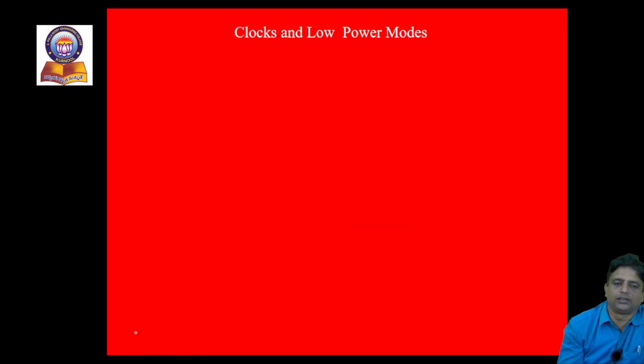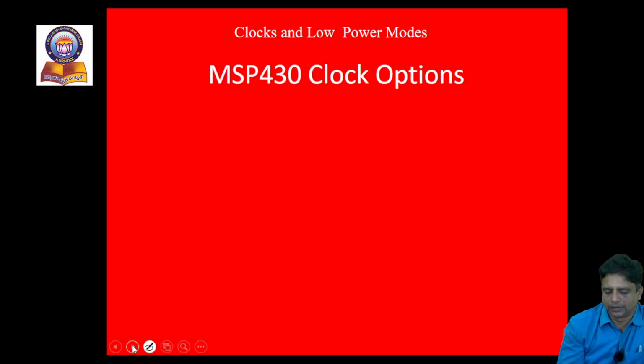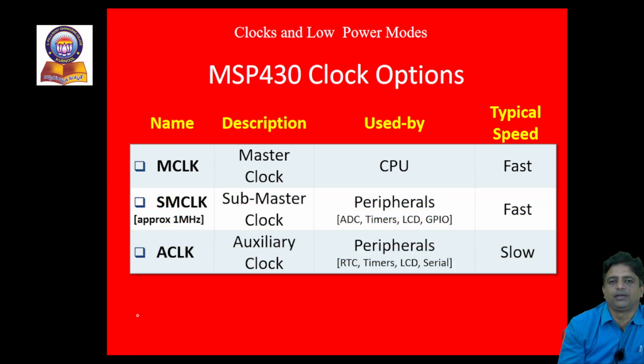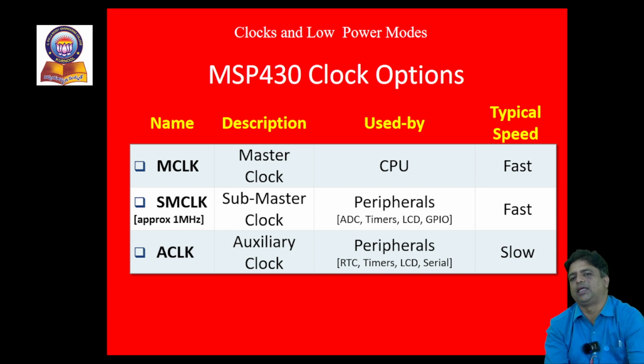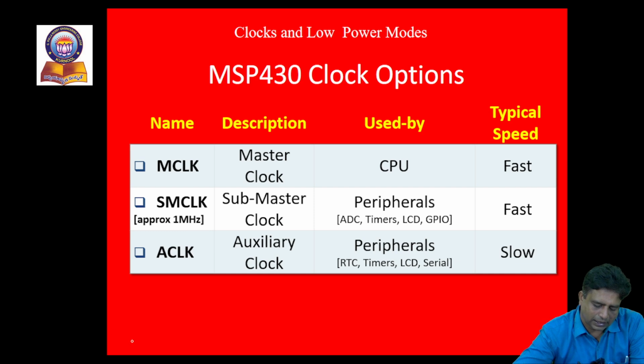In continuation with some more physical arrangements provided with the architecture of MSP430, we can look at the different types of clocks. This is one of the unique facilities provided to the MSP430 processor. In general, clock distribution is very rare in other microcontrollers, but with MSP430 it can be focused on very clearly. Wherever it is not required to utilize the total clock, the system will divert the clock arrangement. It is represented in the block here as master clock, submaster clock, and auxiliary clock.